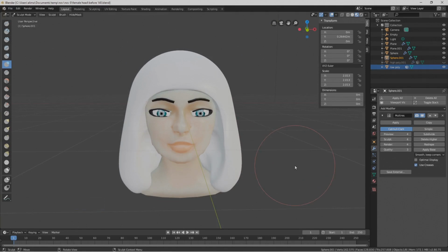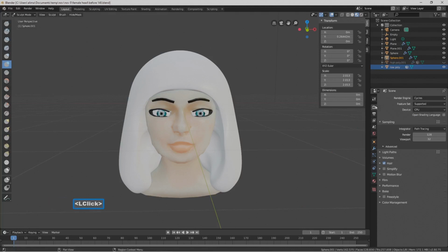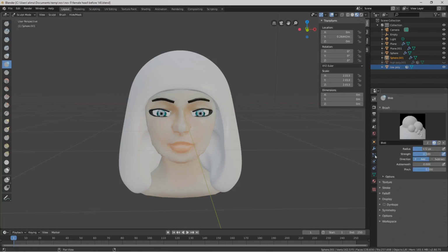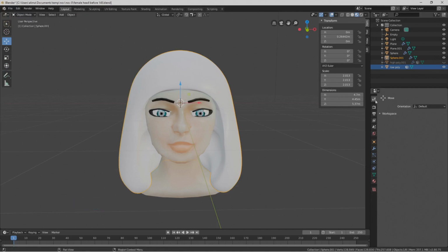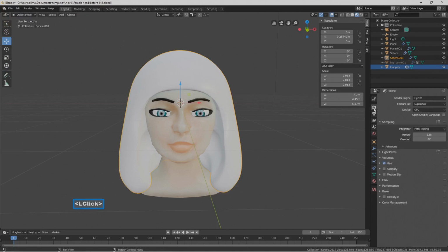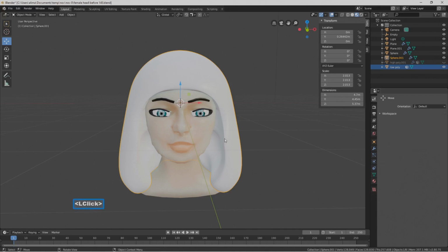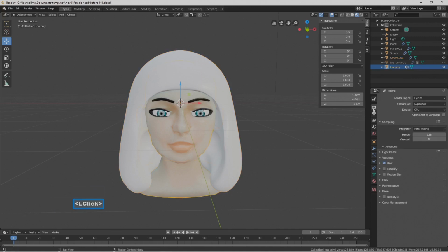Okay, in sculpt mode, there's a symmetry that's turned on automatically. I want to turn off that symmetry. So here's the symmetry right here, and I'm selecting this X to turn that symmetry off. Matter of fact, I'm going to go to object mode while it's on my mind. Just wanted to check something.